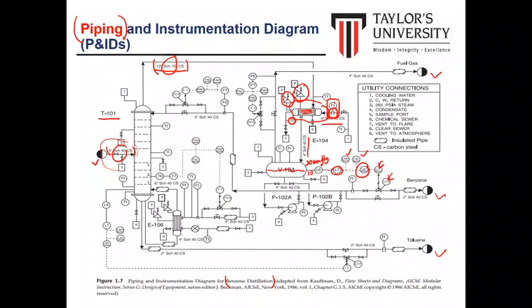So it will trigger the level alarm low. So what happens to the level control valve? The level computer will receive the signal and pass it to the level control valve, telling it to reduce the range from the usual 0 to 100%, to ensure the minimum flow of liquid outlet through this valve.